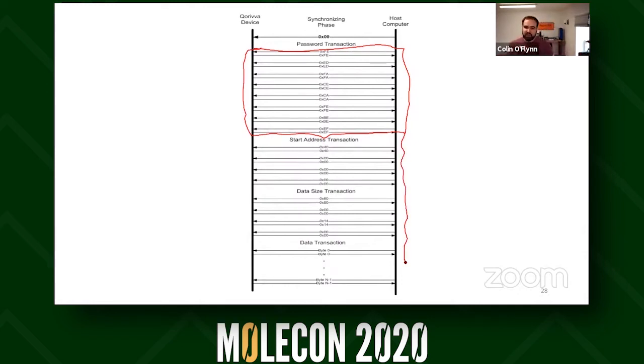You basically need to build a bootloader that's going to run in RAM in the device and then give you access to the flash memory. Before you can do that, though, you need the correct password for the device. Every device has a unique password, so it's not even enough to recover one and then apply it to all. So you need a way to reasonably attack these with some sort of method.